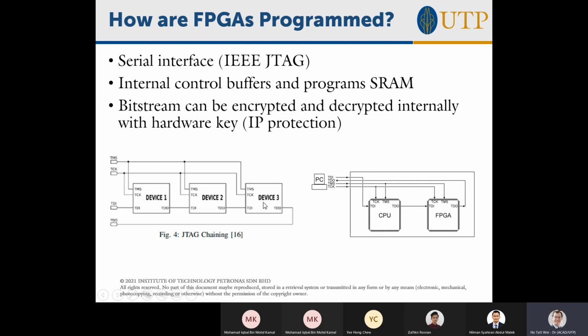If you're not operating in JTAG mode, then your flip-flops are functioning normally, whether it's a processor or an FPGA. Then you have the option to switch to JTAG mode, and all of a sudden all the flip-flops are chained together as a shift register. A controller puts in a clock, and it will shift out all the bits from the flip-flops serially through one pin. This way you can test and read out all the flip-flop values frozen in time. You just read them all out serially using the JTAG interface.